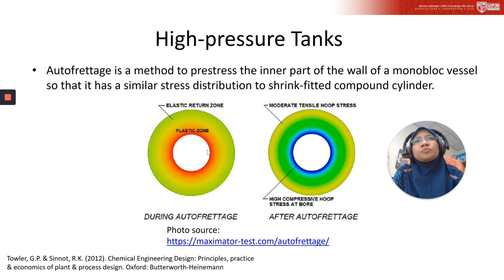During this process, the inner part of the wall will be more highly stressed than the outer part. So this is during autofrettage, and this one is after autofrettage. After autofrettage, you should expect that the inside wall will be highly compressive compared to the outer wall. During the process, it will undergo plastic strain.